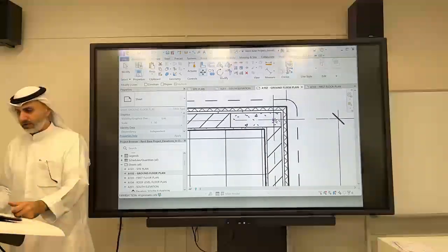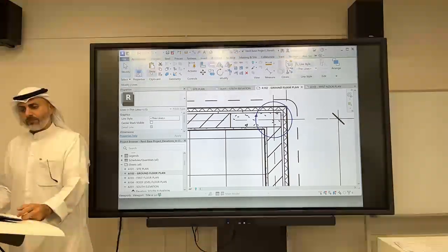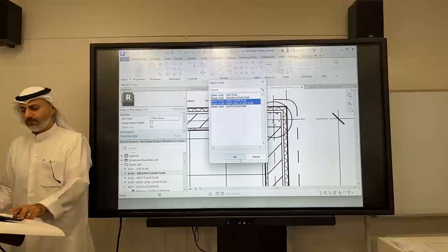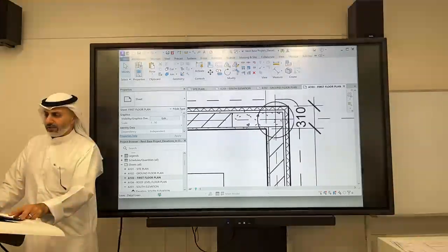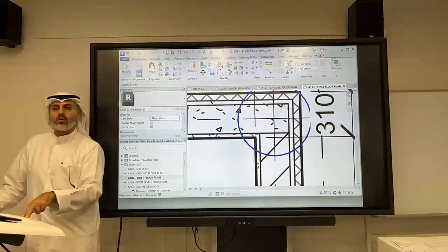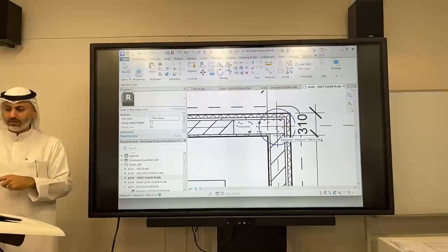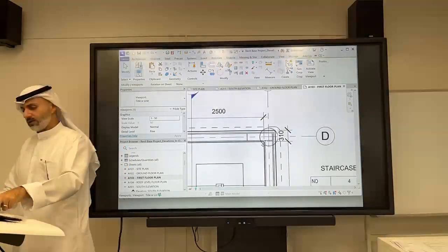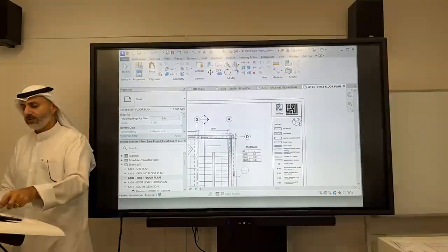So let's say find the 4D, copy it to me, align selected views, and I want my 4D to be the same in the first and roof level. And I check my corner, it's the same, and then you can move your plan so that it lines up to that corner. But if you look at the PDF, you go next, it's not moving up and down, right and left. So you can do that for the model and do it for annotation elements such as the scale, the north arrow. North arrow is always in the same spot.